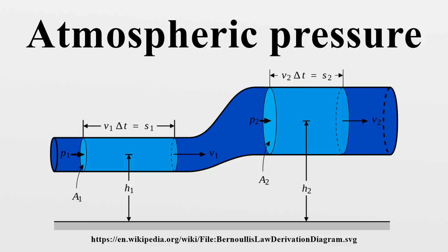The altimeter setting in aviation, set to either QNH or QFE setting, is another atmospheric pressure adjustment. But the methods of making these adjustments are different. QNH is the barometric altimeter setting that causes an altimeter to read airfield elevation above mean sea level when on the airfield. In isotemperature conditions, the altimeter will read altitude above mean sea level in the vicinity of the airfield.